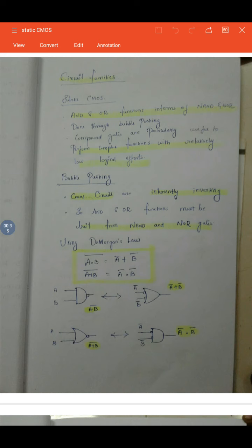And also we are going to discuss the concept called compound gates. This compound gate concept is useful for performing complex functions, and at the same time you can calculate their logical efforts. So first we will discuss the bubble pushing concept.